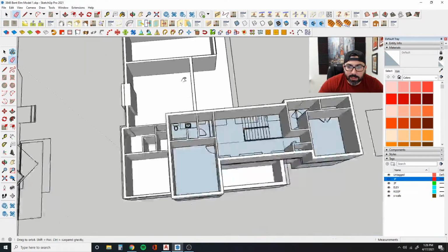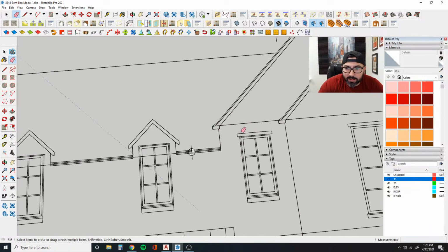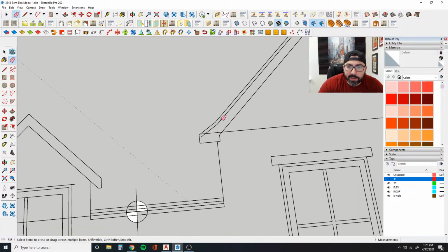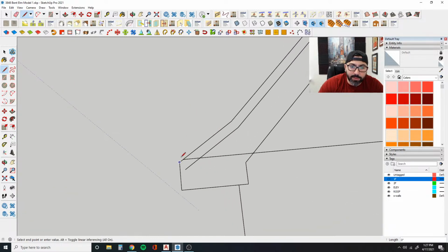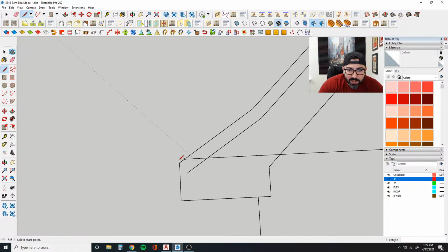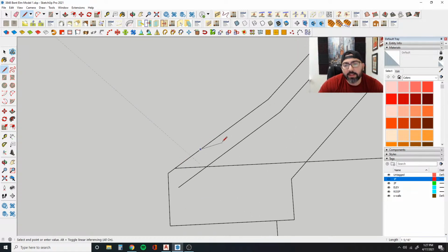And my overhang. Oh, and we have a split overhang. This is called a flared eave. So with a flared eave, we actually have 2 different pitches on our roof. And this made the project just a little bit more challenging. Sometimes if the roof is just one pitch, it makes it a lot easier. Let me see what the pitch of this is.